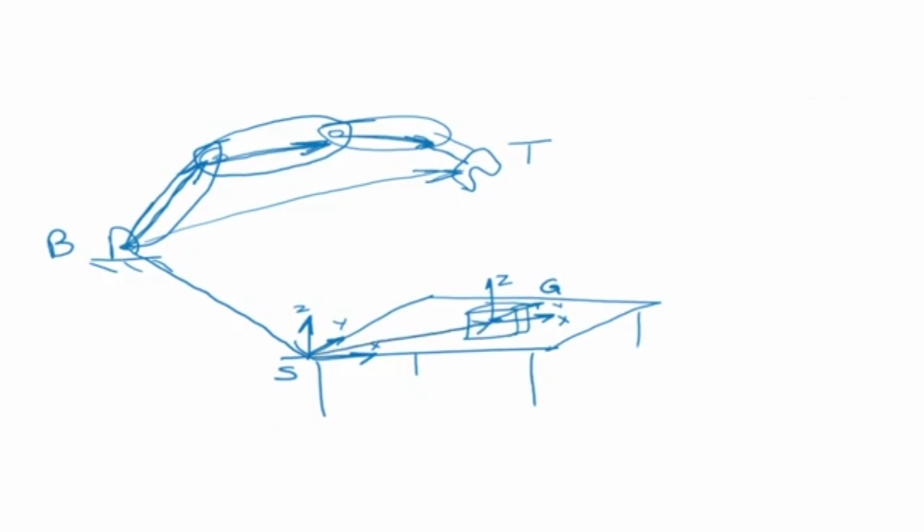So what we have done is attach frames onto each of the points of interest, and this is my x, y, and z. No, z is upwards. So we have attached frames to all the joints and the points of interest. Now what is known? I know this transformation from T B to T. This one is known, this one is known. So B to T is known.